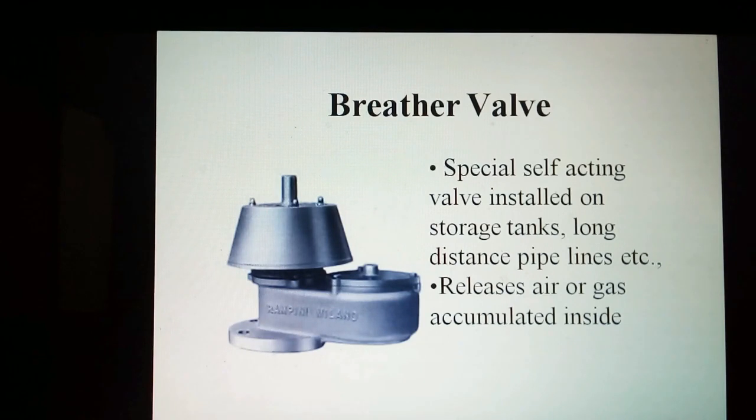The valves prevent the build-up of excessive pressure or vacuum which can unbalance the system or damage the storage vessel. Pressure and vacuum protection levels are controlled with weighted pallets or springs and can be combined to provide the required pressure/vacuum settings. It is common to combine pallet and spring systems in one unit, i.e. pressure settings require a spring section, whilst the vacuum settings use the pallet method.